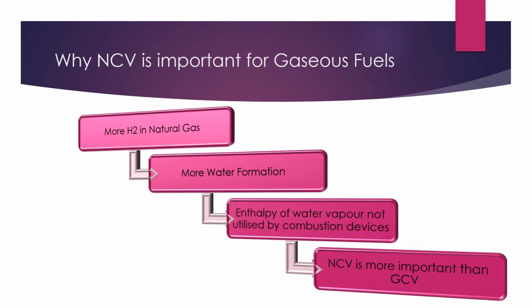Now let us discuss about why net calorific value is more important than gross calorific value in case of gaseous fuels. Coming to one of the gaseous fuels, that is natural gas, it contains more hydrogen. When combustion of natural gas takes place, this hydrogen is converted into water and subsequently into water vapor.